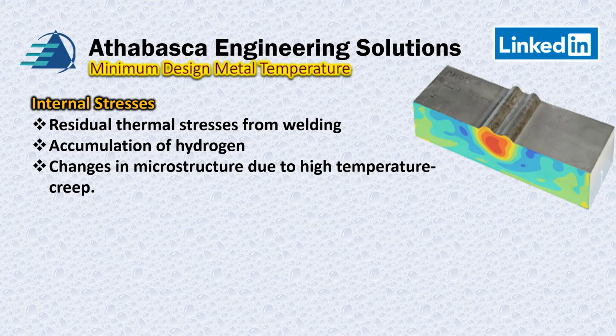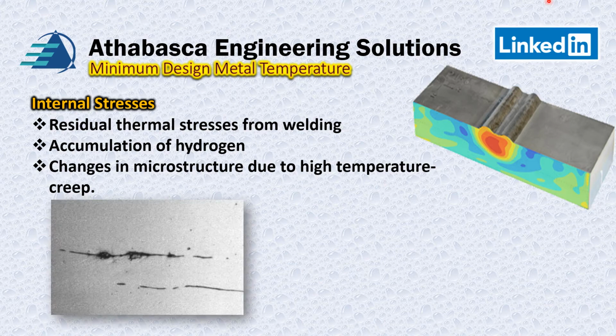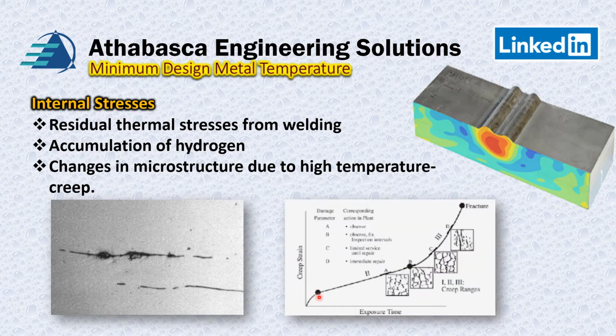And there can also be changes in microstructure due to high temperature. Here's an example of how creep occurs, and we have other videos on that topic about creep, but you can see how the microstructure, when you're operating in the creep range, can change, and the grains can get enlarged. You can start to see cracks in the grains, and that will also affect the minimum design metal temperature.